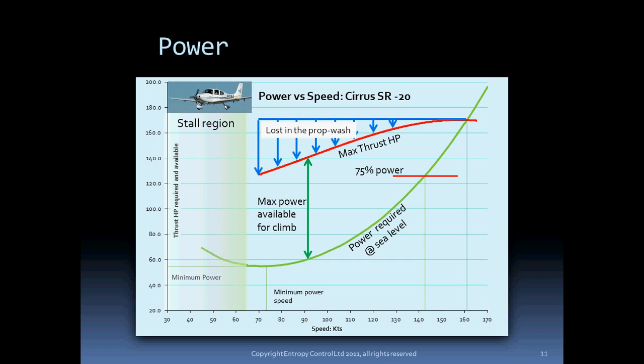Except, of course, in the Cirrus, where you probably would pull the chute rather than risking any kind of forced landing. But I suppose that the training based on best glide has a lot to do with keeping a panicky pilot away from the stall speed. Best power speed is always uncomfortably close to stall speed.